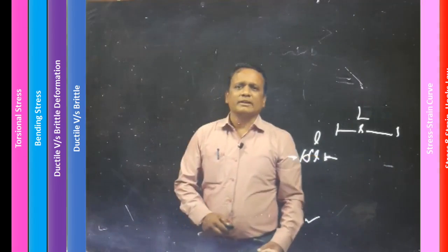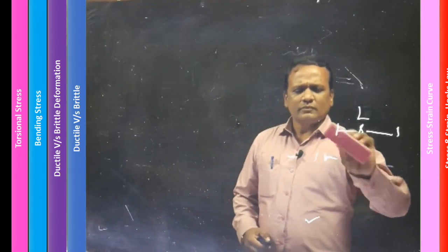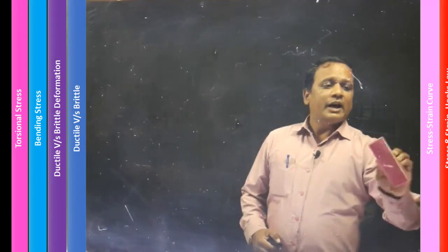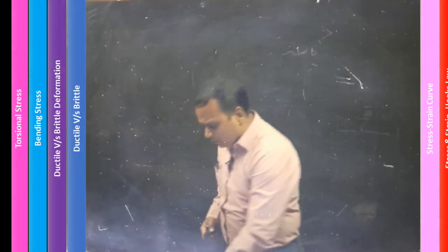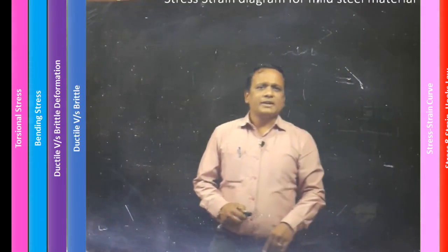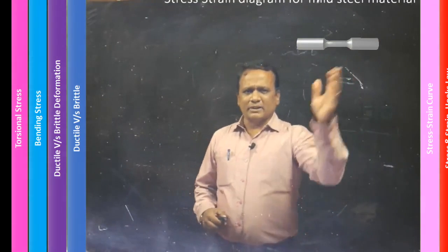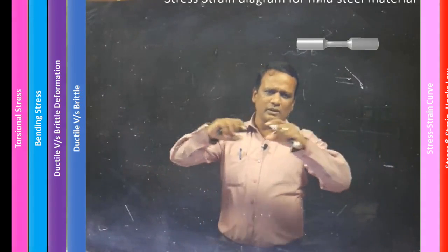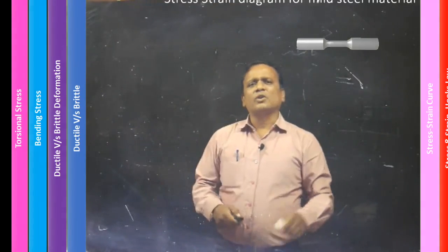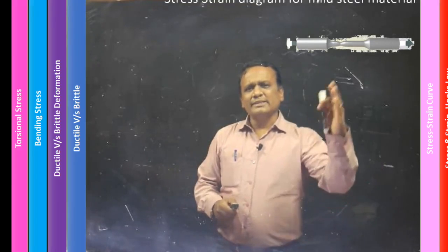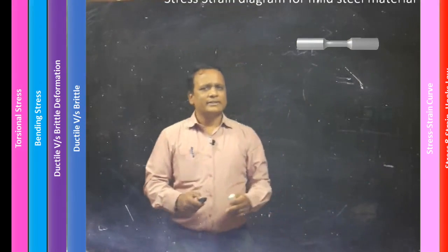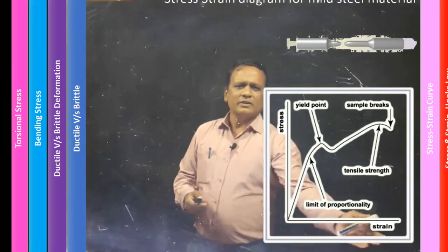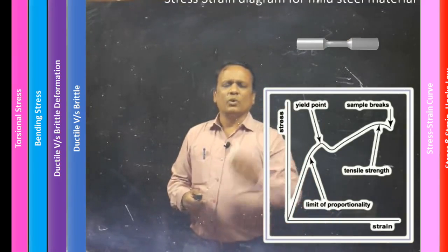Now coming to the next part, how do I check the stress-strain diagram, for which again I will take up one example, a dog bone specimen under a tensile load. Consider this particular dog bone specimen under a tensile load all across. While doing this, the whole specimen tends to pull and undergo a deformation. To explain this deformation, I would like to use this curve, the stress-strain curve, with strain on the x-axis and stress on the y-axis.